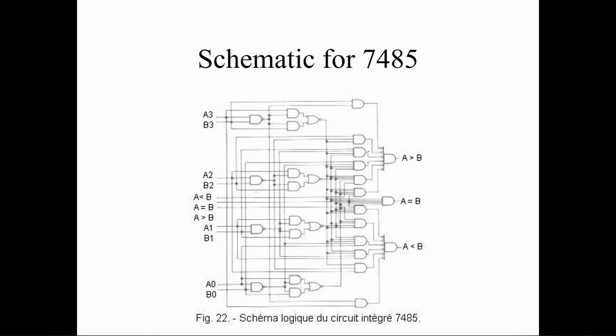And then the way it comes out of this signal is it feeds into another AND gate, rather a couple of them here as well. And then with this, we are able to get outputs that are three different ways. We are comparing A to B, looking for greater than, equal to, or less than on the output.